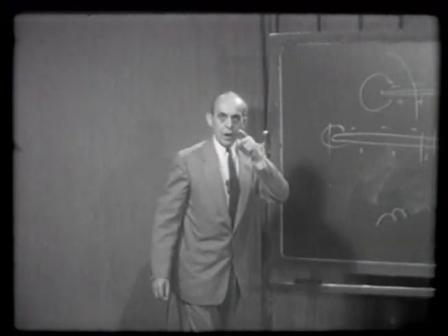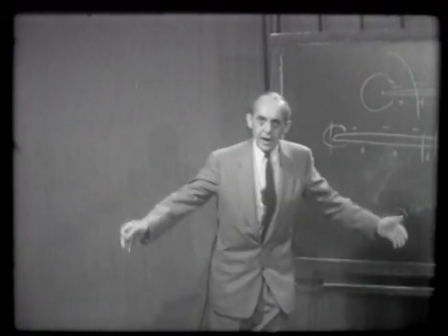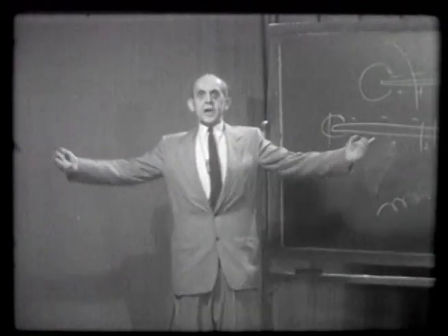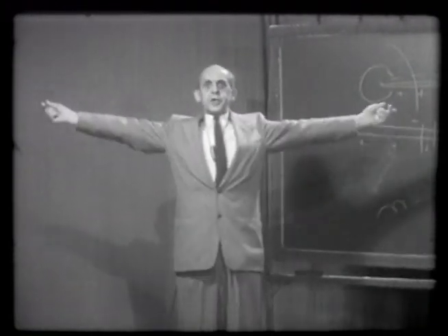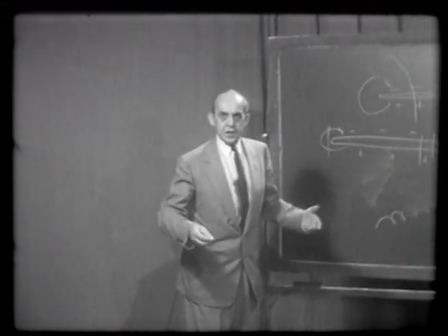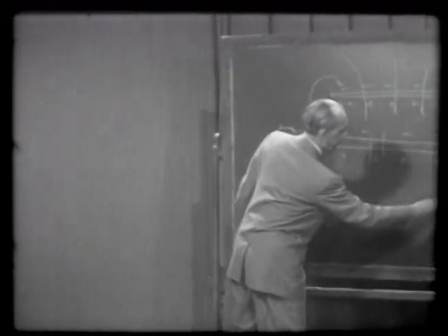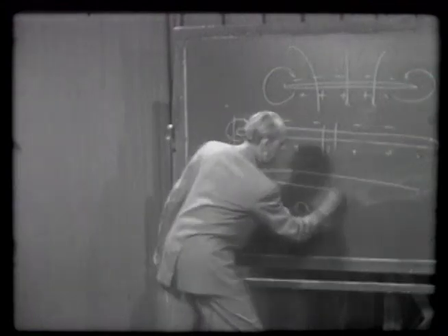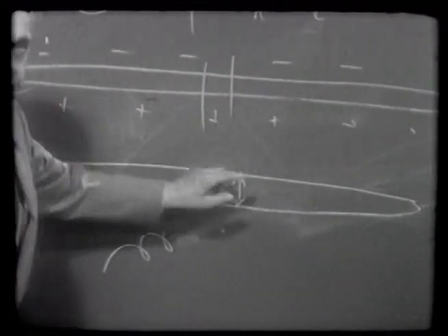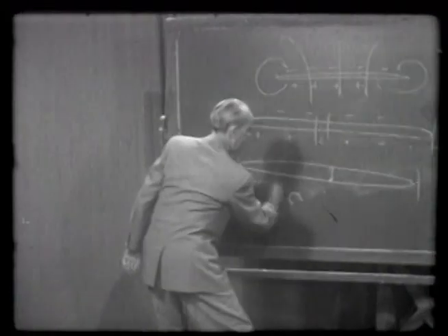And that is the reason why, for a highly economical aircraft, we should have wings which extend into large span. And since we cannot increase the surface of the wing, otherwise we would get too much surface friction, we have to have a very slender wing with a small chord, the chord length we call from the leading edge to the trailing edge, and a large span.